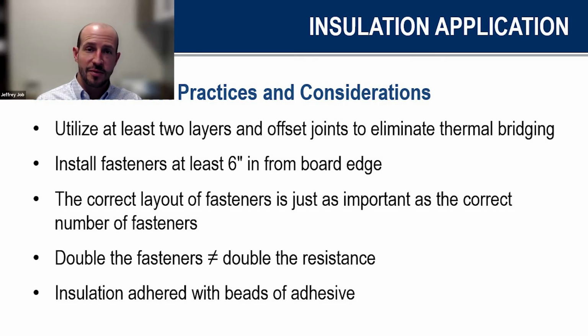Another benefit is going to be your fastening patterns. It's a more rigid board than your typical insulation, so it's going to have more wind uplift resistance. With that said, you can oftentimes get away with fewer fasteners in an adhered system. If you're having preliminary securement of that coverboard through the insulation package before you adhere your membrane, oftentimes you can use fewer fasteners than you typically would need if you're going direct to the insulation below. So that's some of the trade-offs there.